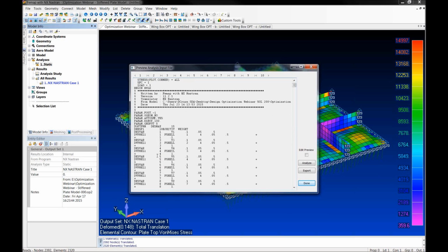And if we go down here a little bit, this is the d-optim parameter, design variable max iterations 15, just to give you an idea. And you can see it auto-filled in our definition. So here we have our objective function. We're going to minimize weight. We have our first design variable ranging from 0.05 to 0.5.